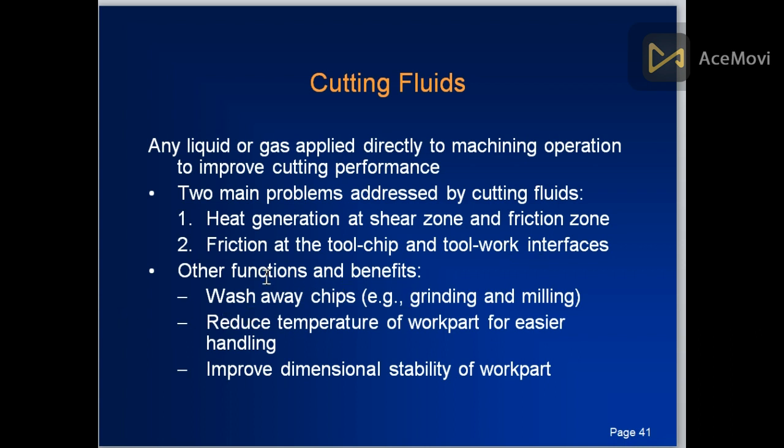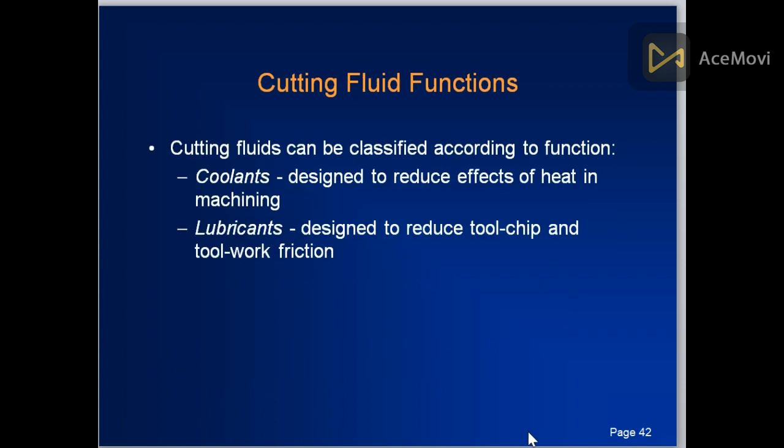Some of the benefits, apart from heat reduction and friction reduction, are that the fluid can wash away the chips. It can move the chips into channels, reduce the temperature of the work part for easier handling, and improve the dimensional stability of the work part. This is stability of the dimension, because as the temperature does not rise, the thickness remains the same.